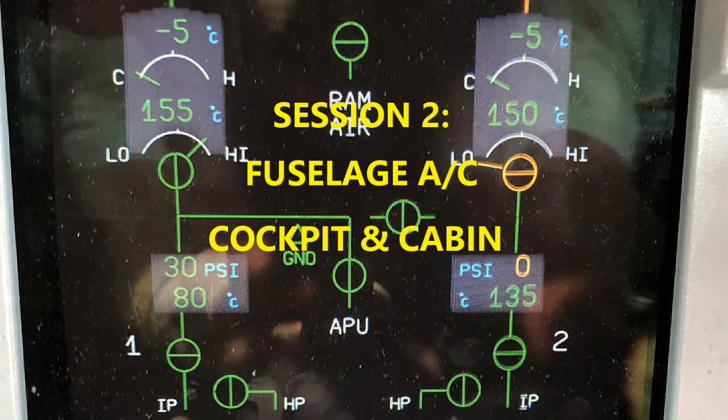There's also a pack outlet pneumatic sensor. Those are installed on the condensers and connected to the anti-ice valves. Let's say a pack controller doesn't work. Then the pneumatic sensor transmits the pressure to the applicable anti-ice valve. If the pressure at a pneumatic temperature sensor increases or decreases, there's your differential, and that valve opens or closes to maintain the pack outlet temperature. So it uses the pressure at a temperature sensor to maintain that outlet temperature at 15 degrees Celsius. Remember, the air conditioning pack outlet temperature needs to be maintained around 15 degrees Celsius.